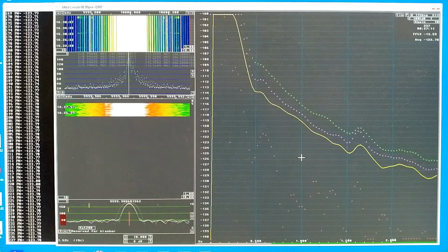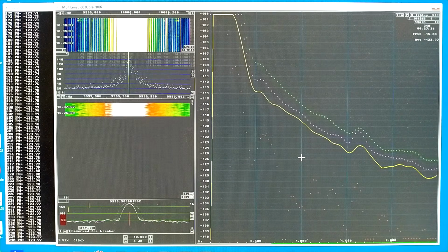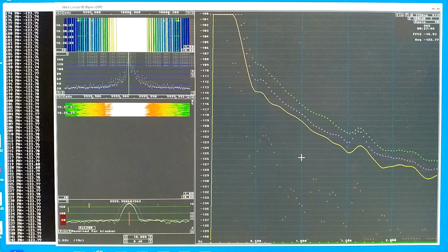Now I want to measure something like minus 132 dBc per Hertz for my best oscillator. That is 13 decibels better than what I have here, means 20 times lower, means 400 times longer measurement time. That's a long time. So I cannot hope for as accurate measurements, which makes optimization a little bit harder.